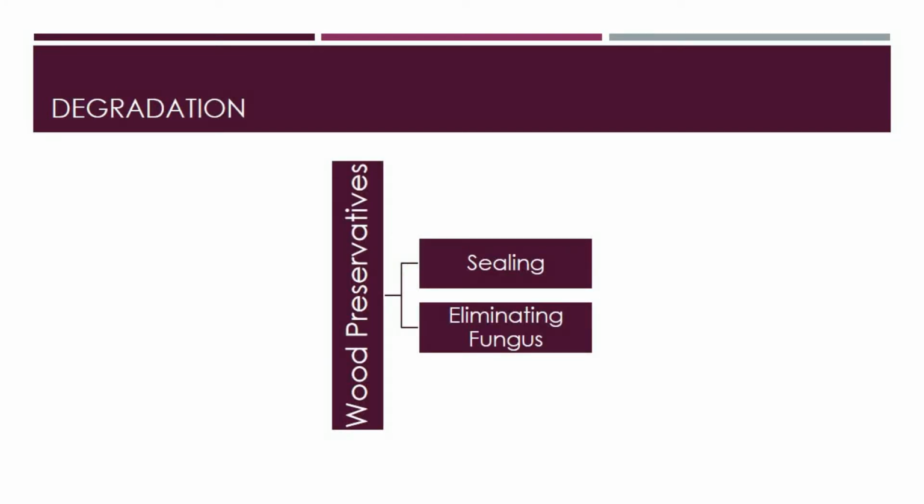Because wood is a natural product, its decomposition differs from that of other assets in distribution system. Biological and environmental causes such as fungal decay, wildlife damage, and weather effects are the most important factors in the degradation of wood poles. Fungi affect wood poles' external surfaces as well as their inside heartwood.